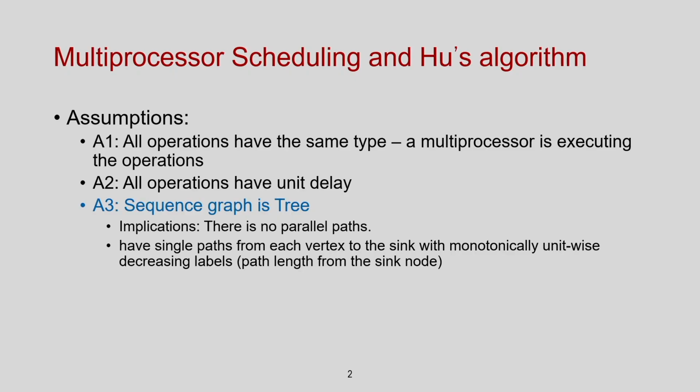Welcome students. In today's class we are going to learn about some heuristic based scheduling, specifically the list scheduling for the MLRC problem. If you remember, this scheduling, where we assign time steps to the operations, is in general an NP complete problem. The primary reason is that once you try to schedule an operation at a certain time step, say time step 1, and the number of resources available is k, there may be more than k operations available to be scheduled in that time step.